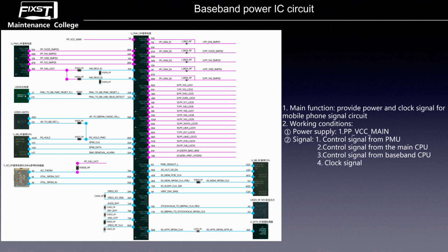And continue going down, you can see the 13.2 line. This line is the SIM remove signal. This line works for removing the SIM information. Its function is only for when we remove the SIM card, it will delay and clean the last SIM card information.